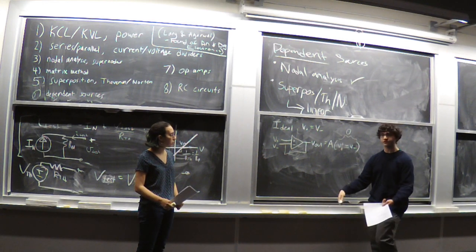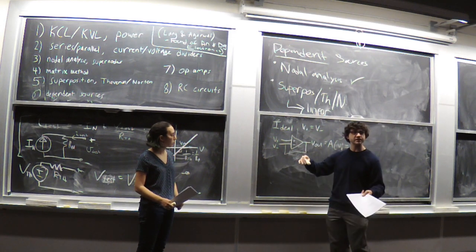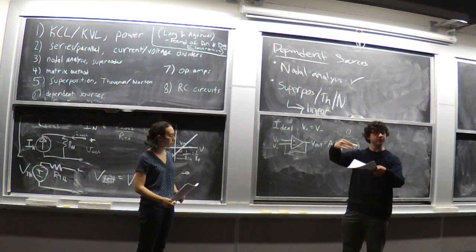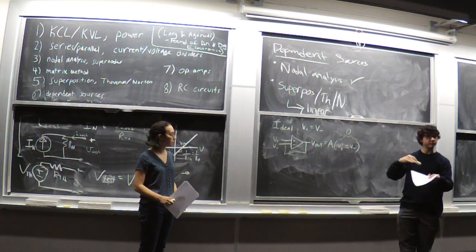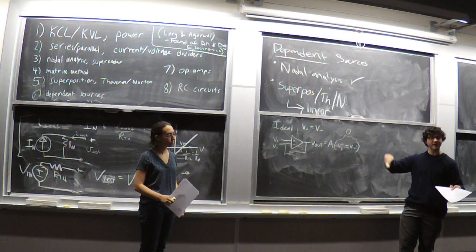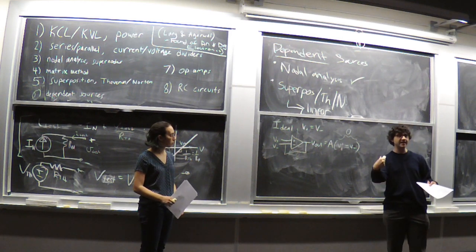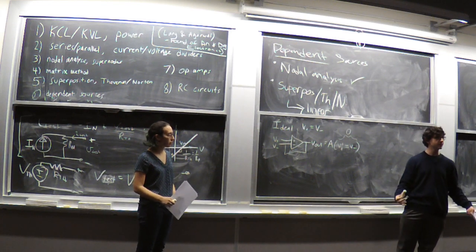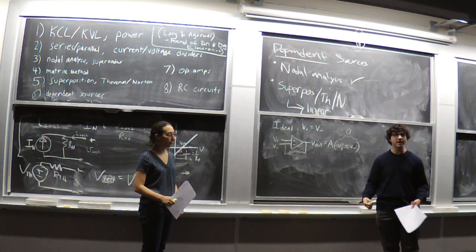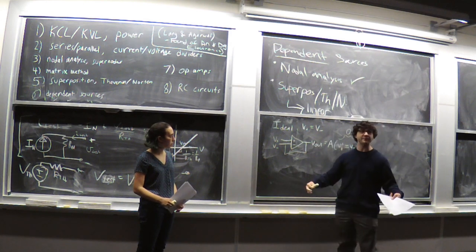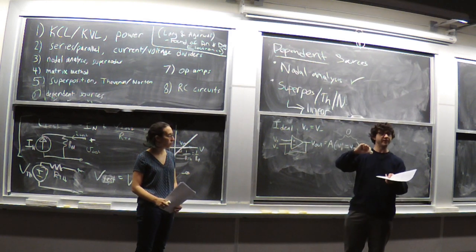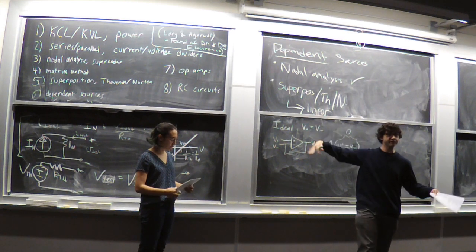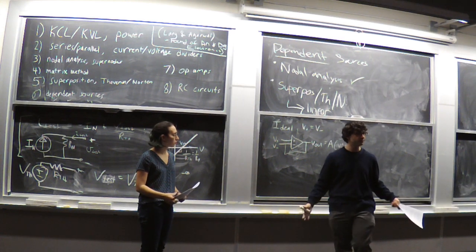What happens when V out starts rising? Well, since it's tied to V minus, that starts rising too. And it rises until it's reached V plus. And now this is back to 0 and we've stabilized again. And so by tying that output back to the negative terminal of the input, we do this self-correction mechanism that prevents it from getting unbounded. If we were to have positive feedback, the opposite thing would happen. If we got a little bit off center, then it would exponentially shove itself further and further off center, and it would be really, really unstable.